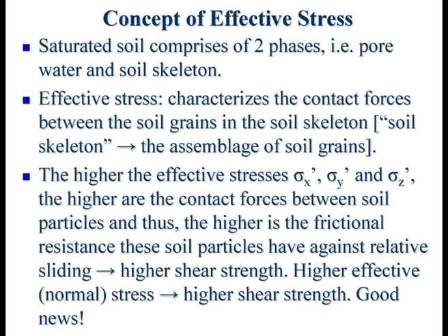And very often, a high effective stress in many circumstances is a good thing. It's good news. Think of liquefaction, those of you who do earthquake engineering. Liquefaction means what? Zero effective stress. That's bad news, no? That's real bad news. So high effective stress is not bad news. High stress in soil is not always bad news. That is the second cultural difference between soil and structure. In structure, high stress is bad news, but in soil, high effective stress is usually good news.